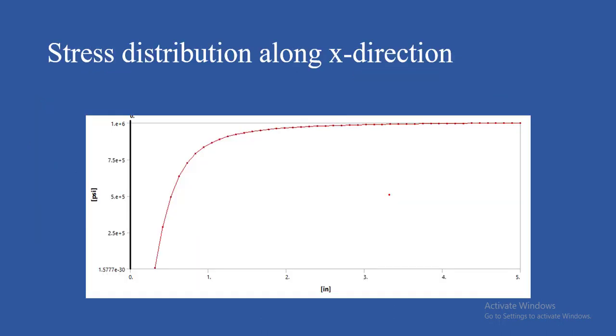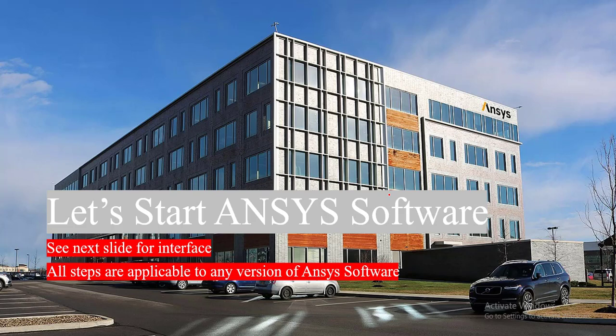And we will define a graph within ANSYS Workbench software in which we will use the length of the plate along the x-axis, and on the y-axis we will plot the normal stress to determine the distribution, how the stress is increased rapidly along a stress intensified section, which is the hole. Now we will go towards the ANSYS software for performing this analysis.